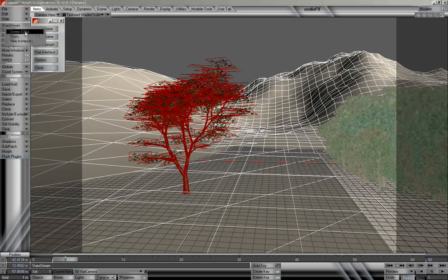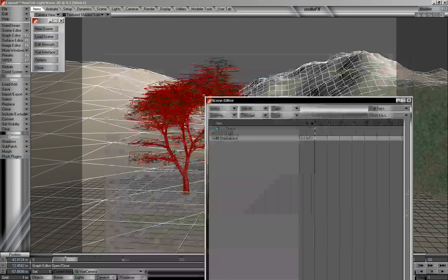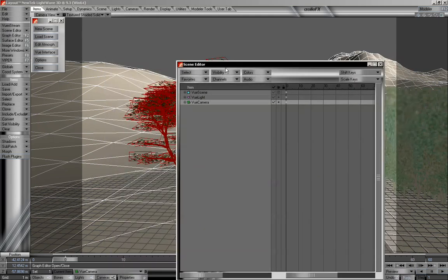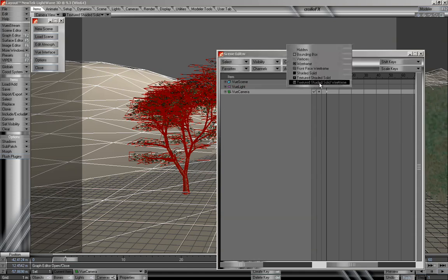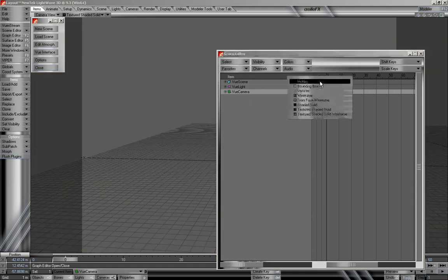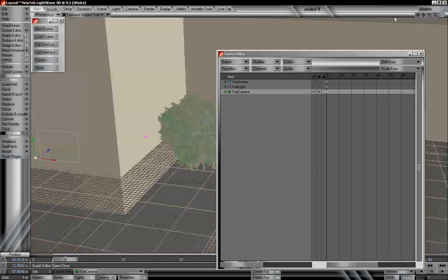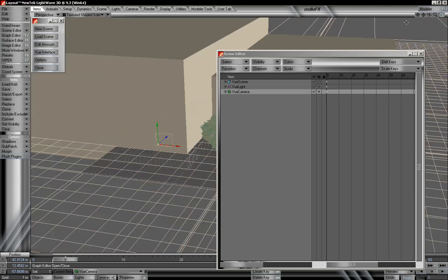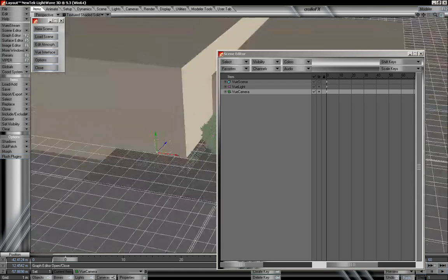If we go into our scene editor now, we're going to take a look at actually changing the view without using our viewport methods, because that's really what we're going to have to do in order to change this to wireframe and some of the other settings. So we take a look under where the eye is, and now we can change these to all the different modes. If we go to hidden, our scene will disappear completely. Bounding box, right now in this state, we're just going to see huge bounding boxes for our different terrains, and the trees that are instances are showing up.